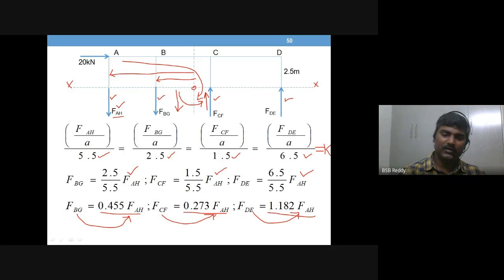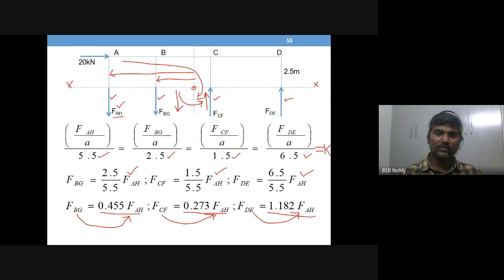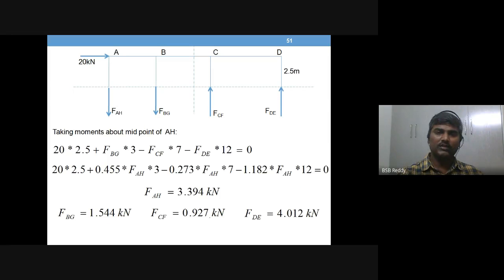Now you need one more equation because you have four unknowns. There are four columns, four unknown axial loads. So you have three relations possible from assumption 2. The other one should come from the existing relation that moment at the point of contraflexure is 0.